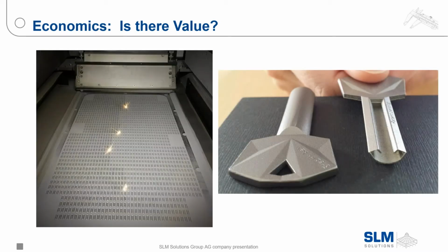One of the rules of thumb is that one SLM machine will produce about a ton of material a year. So we need to understand how much you are looking to produce, to understand how many machines would be needed to produce the required amount of material. So if it's 5,000 kilograms a year given by the design, that would be about 5 SLM machines needed.